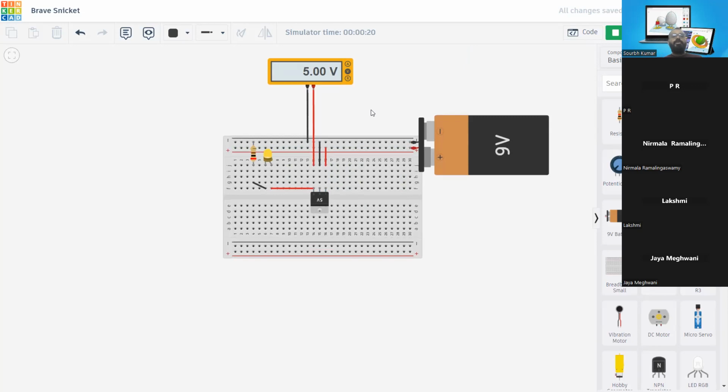We can achieve the same thing with a resistor as well, but a resistor is not ideal, because whenever we try to convert a higher voltage to a lower voltage using a resistor, more friction is produced inside the resistor, and then the resistor will start emitting heat. It will convert the electricity to heat energy and cause losses of power in the electric circuit. So for ideal use, we should utilize regulators in our electrical circuit or any project circuit to make it perfect in all senses.